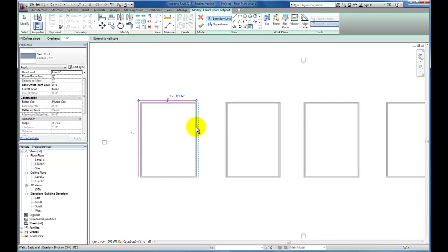And you'll see Revit actually cleans up this sketch for me as I select my exterior walls. If I need to switch the orientation of my wall, I still have this symbol, and you'll see it actually brought the sketch to the inside face of both of my walls, 1'6". I'm going to keep that on the exterior, and this right here allows me to change the slope. So I'm going to deselect out.